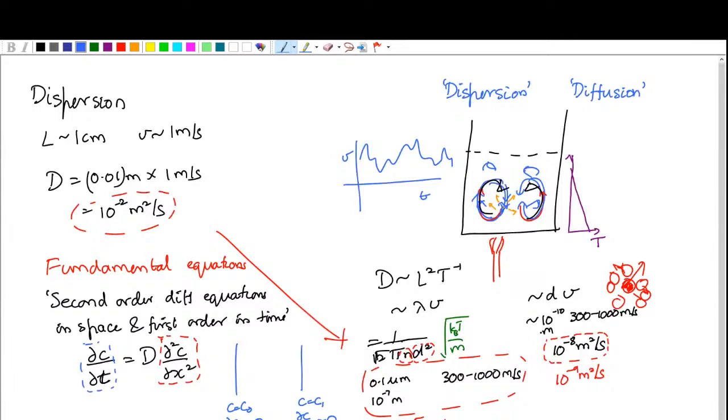Okay? So, for example, if I have a PFR here, okay, you know that we plot the velocity profile as some kind of a laminar velocity profile. The velocity at the wall itself is set equal to 0. Okay? That is because the pipe is not moving, so the fluid at that surface has to be equal to 0. Okay? And then it increases towards the center because there's a pressure force that is driving the flow. Okay? And for a laminar flow, you'll get a parabolic velocity profile. For a turbulent flow, you'll get something that looks more plug-like. Okay? But in both cases, the velocity has to decrease to 0 at the wall of the pipe. Okay? That is a necessary condition.